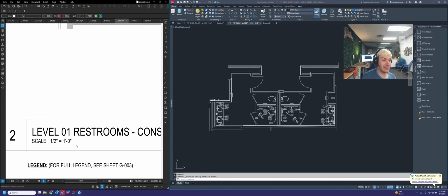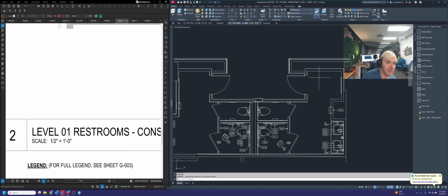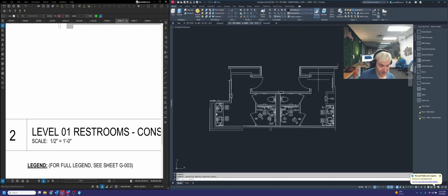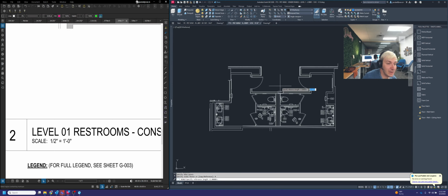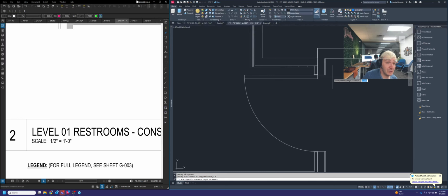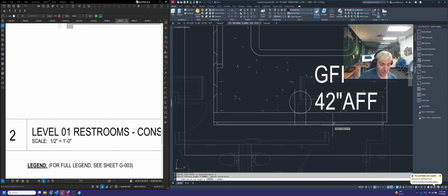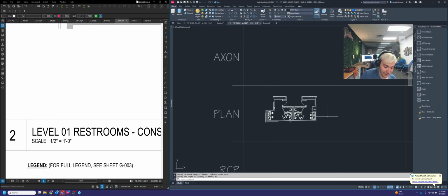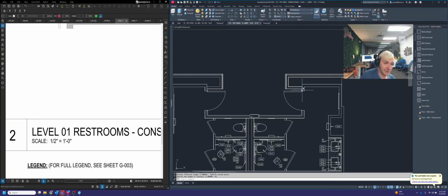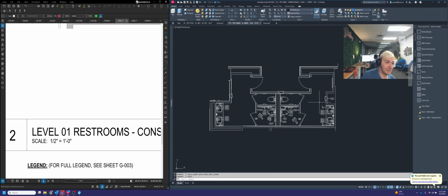There's two ways to go about doing this. If I knew what any of the dimensions were for the drawing, I could use the scale command, and I could use what's called a reference scale. So if I scaled all my objects, picked a base point, and then typed in reference, it will ask you for 2 points to select. So if I knew what the distance was between here and here, let's say it was 42 inches, I could set that scale and it'll increase the size of the entire drawing to make that 42 inches there and scale everything up at the exact same rate.